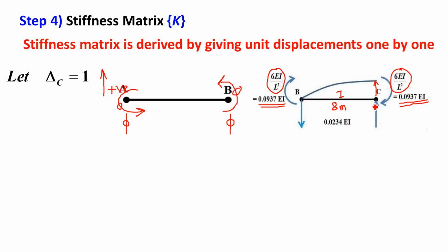To give the vertical displacement, you have to apply the clockwise moment. But if you are confused to decide the nature of moment, there is a simple way. You draw one arrow in the direction of displacement and bend that arrow outside the beam. Automatically you will get the nature. It is clockwise, right?